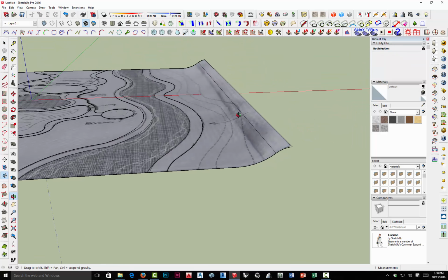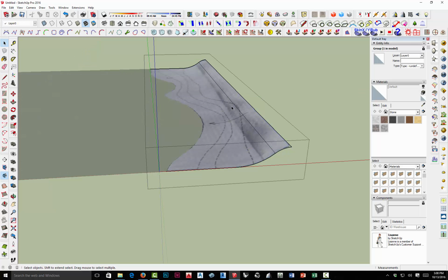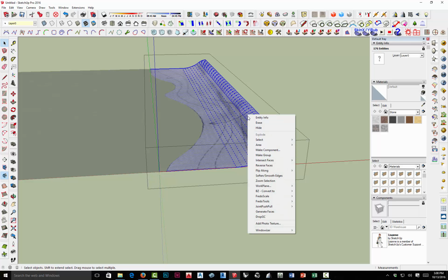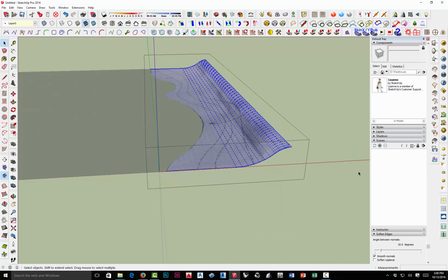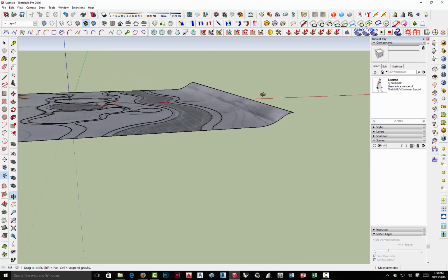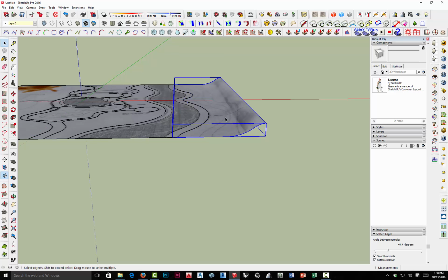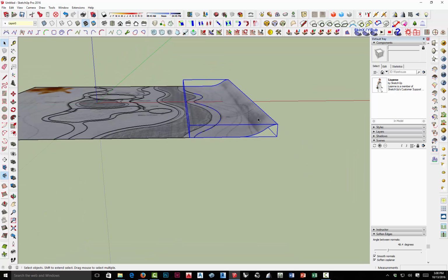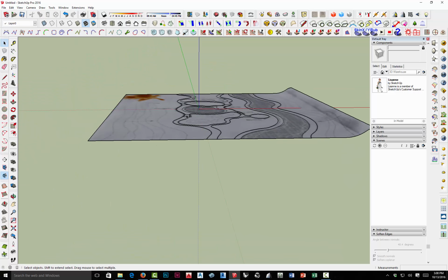Later on, I want to smooth this. I'm going to create a mesh, so for right now, I'm going to double click. If you see a line show up, then just triple click on the surface, right click, choose Soften Smooth Edges, and under here, down here, I'll go Soften Coplanar and move this over to, I don't know, 48, 50 degrees. So now when I get out of here, that's nice and smooth, and that will work well for using the soap skin. Let's go through that same process on the other side.